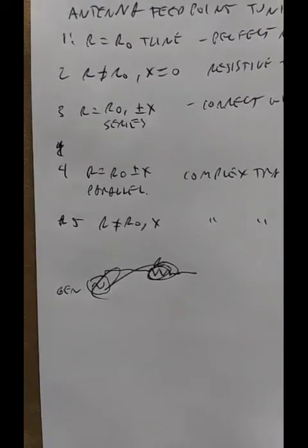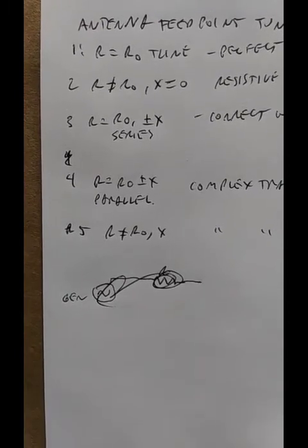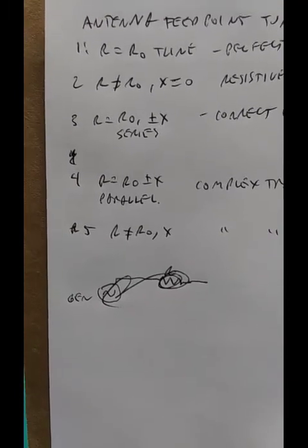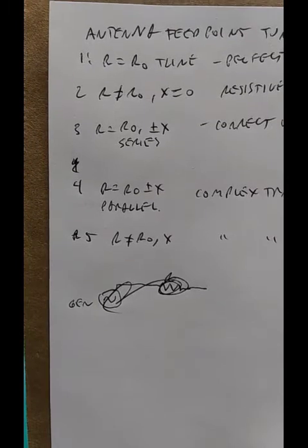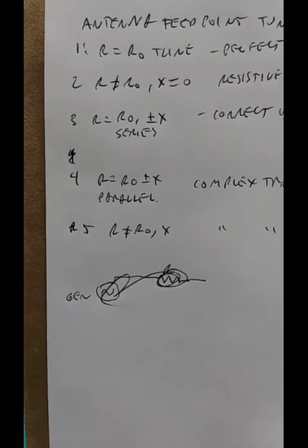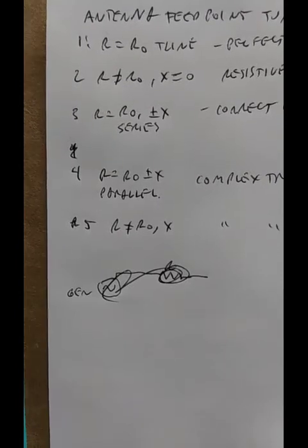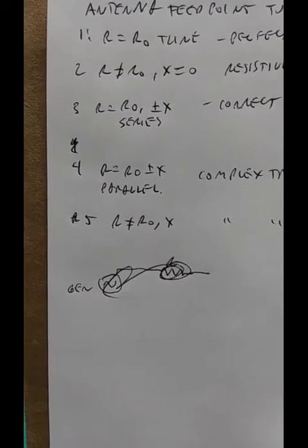What that complex conjugate network does is allow transforming resistive values only, not reactive. It is an absolute myth that we can take a feed point with R plus X and use a tuner to tune that out. Can't be done. It says so in the Radio Engineer's Handbook, written by a PhD. ARRL doesn't like that. Tell them to go read the book.